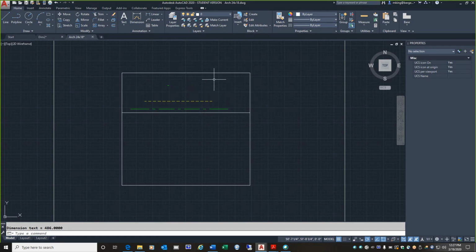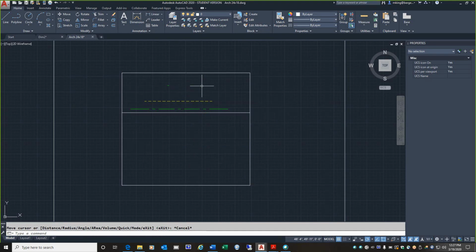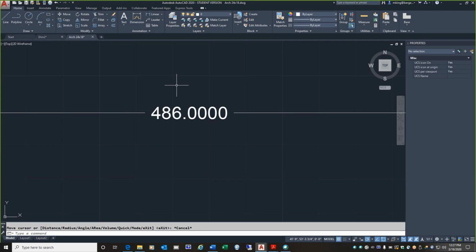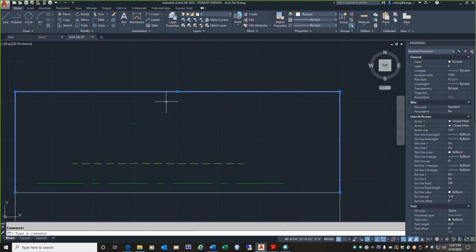Where's my number? They are there, but they're microscopically small because remember, if we use the quick measure command here, if I click that quick measure and I put my mouse inside, this is a 40 feet 6 wide rectangle, so this is much bigger. Now watch this. If I put my mouse near the middle of this dimension and zoom in, it'll take a while, but there is actually a number there, and it's decimal, and it's 4 places, so there's everything wrong about that. So I'm going to zoom back out, delete this whole thing, and then let's do this the